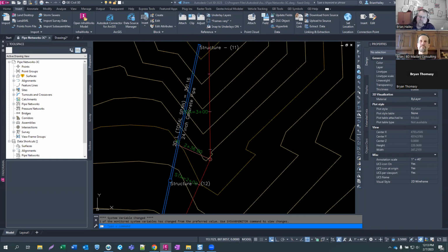So you would XREF that into other drawings. And then you have the drawings where you can data reference stuff out of. And those are the model drawings. And so you would take your line work drawings and XREF them into your model drawings to create your models. Now, your model drawings really don't get XREF'd anywhere. They're data referenced out, right? And so you XREF back and forth between your line work drawings, you data reference back and forth between your model drawings, you XREF into your model drawings, and then you have the production drawings, all right?